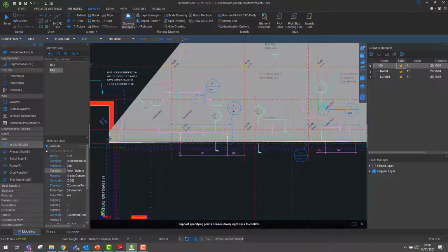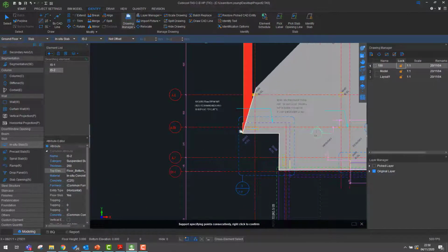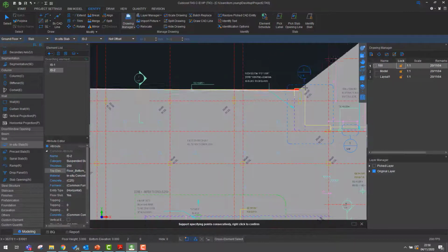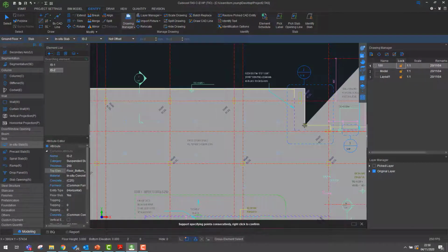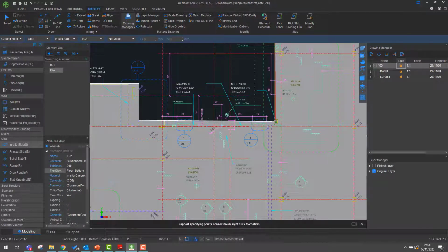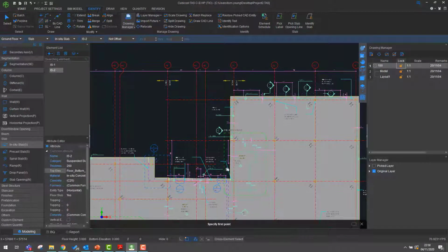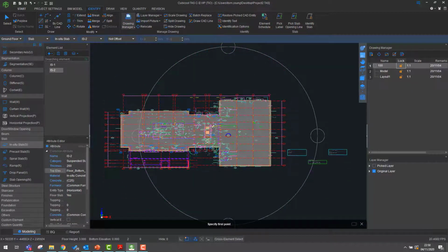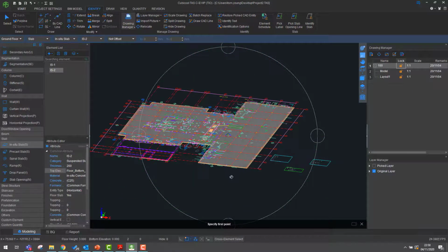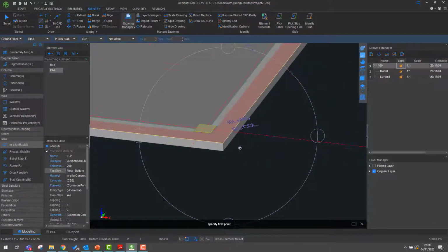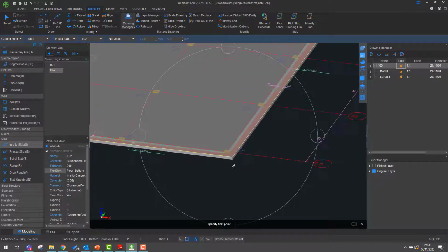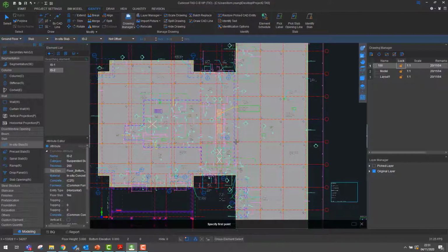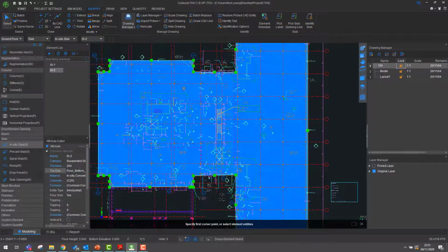So just placing in the slab to give you an idea of how that looks. And you can see that the item itself is being drawn in. Now this isn't an area measurement, this is the actual slab being placed in, and it is also being placed in 3 dimensions. So let's just look at this. We have a 3 meter floor by default, and I can see that that 200 mm slab is in there, and the drawing is overlaid on top of it.